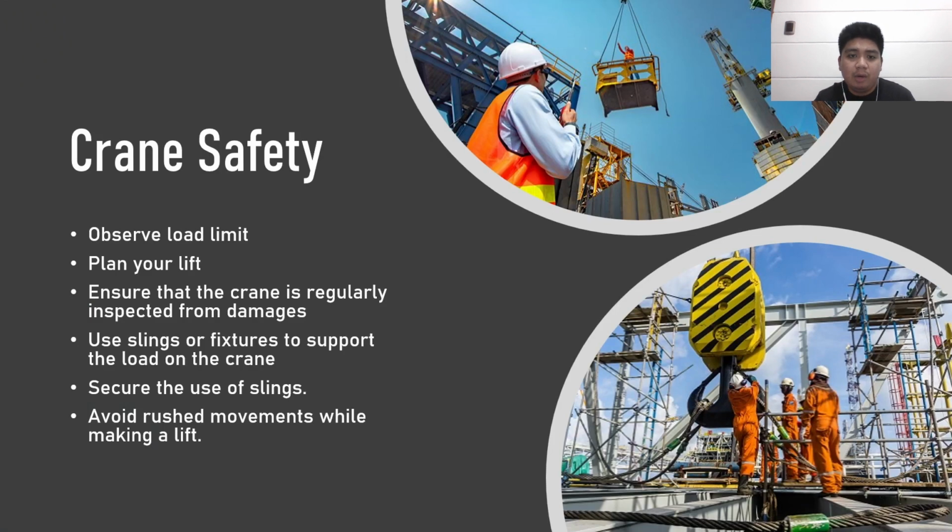First, require workers to always check the crane's load chart to ensure that the crane will not be overloaded by operating conditions. Remember to not engage in shock loading, because if the crane's load becomes too heavy, the crane may be subjected to irreversible damage such as swinging or sudden dropping of the load.